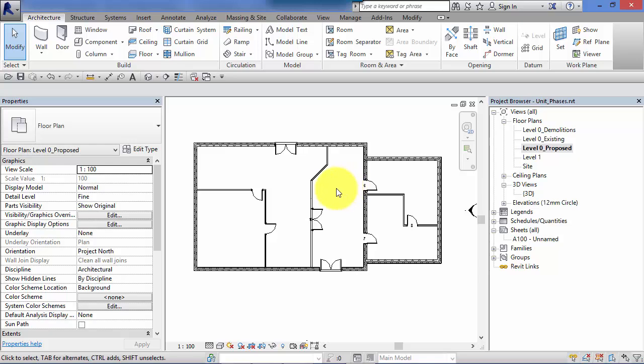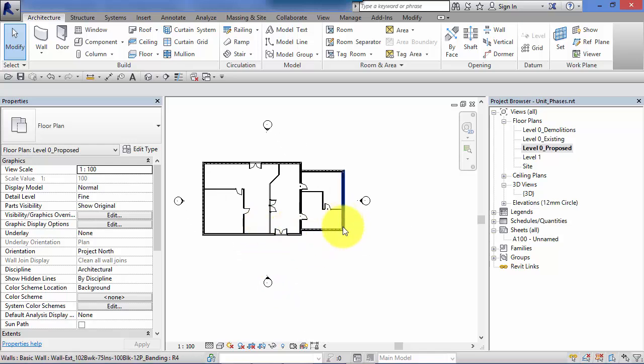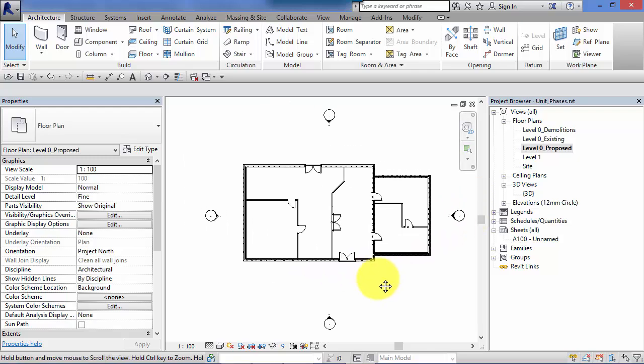So if you've got a large development that's built in stages, let's say a school or university campus where you're building different blocks at different times, you can model that whole development in one Revit project file using phases, setting those milestones at each phase and having your model adapt and extend and new blocks built at those various points. So that's the correct way to handle existing and proposed and multi-phase projects. Please do not model your existing and then just copy it to represent the proposed. It's not the correct way to do it in Revit.